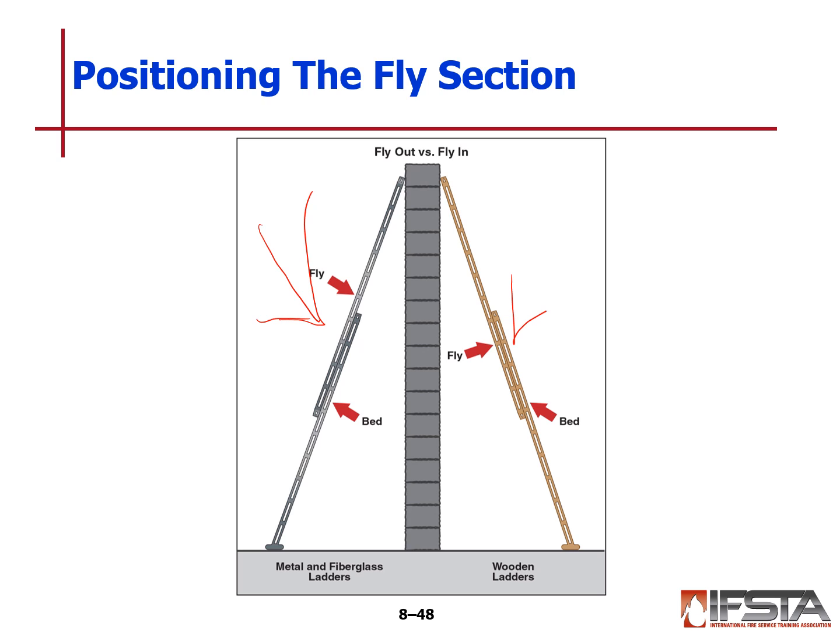The wooden ladder that we see here, the fly section is in, or it is towards the building right here. So fly in for wooden ladders if you have them, fly out for metal and fiberglass ladders.